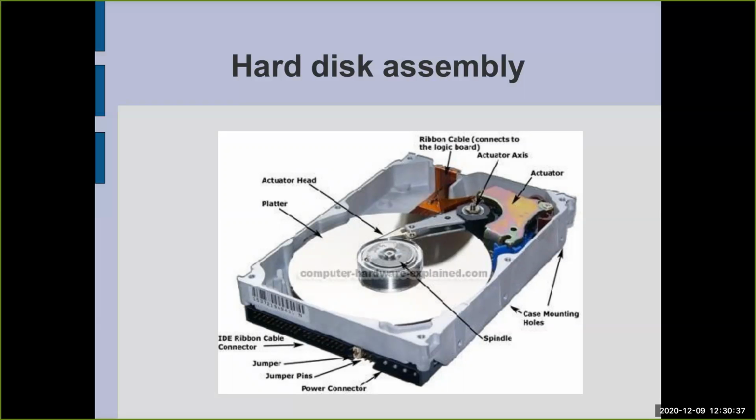So if the accelerometer detects a free fall, so it detects that your computer or hard drive is falling down, it powers off. In this case, the arm is parked, and when it hits the ground, nothing should happen. But okay, don't try it. There is a protection against it.